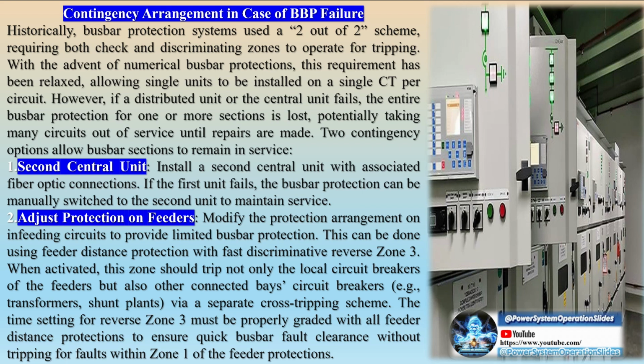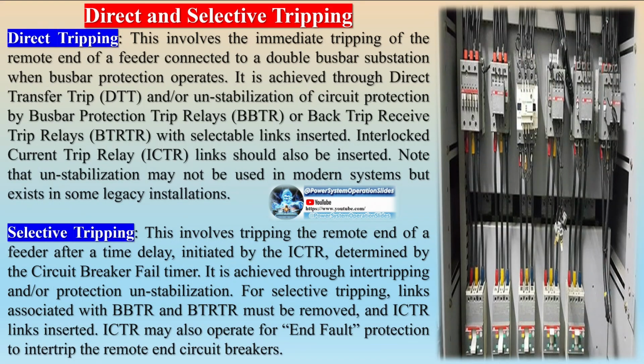Substation configurations may require an additional trip criterion, such as check zones. The check zone measuring system detects short circuits across the entire busbar, disregarding disconnector positions. Disconnector positions are only considered in special cases, such as for transfer or combined busbars. The entire substation is treated as a single node, summing the currents entering the node according to Kirchhoff's current law.